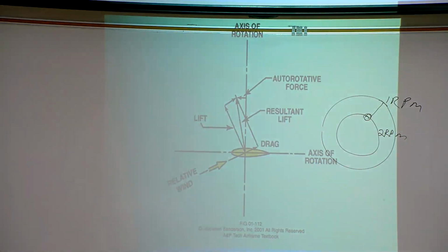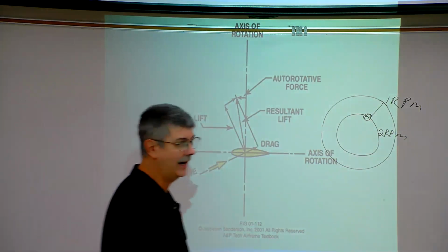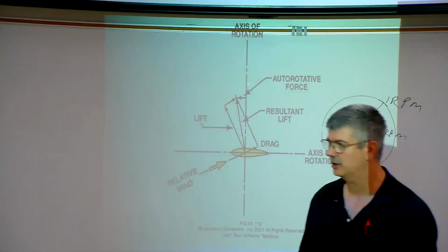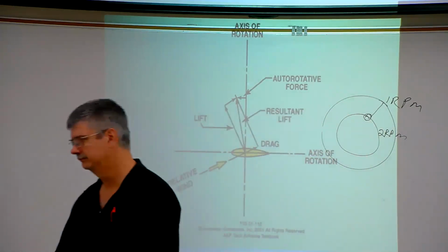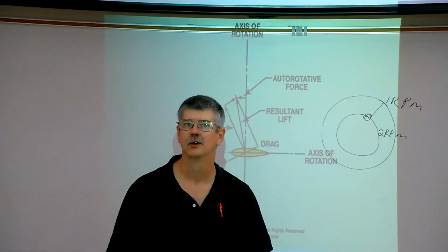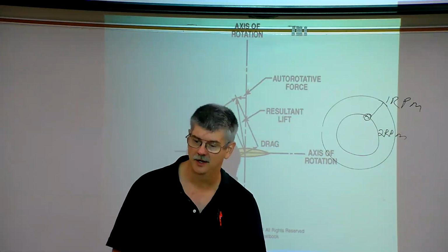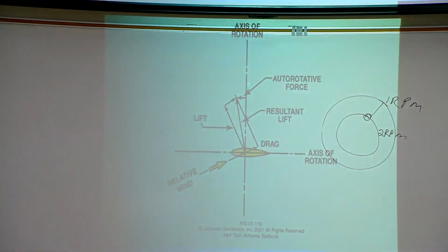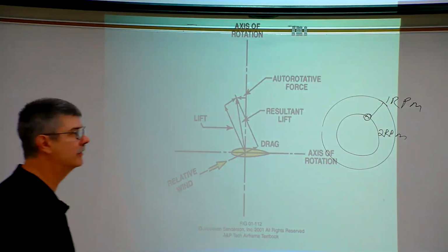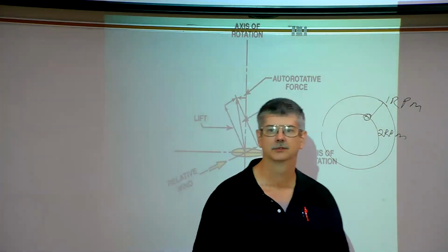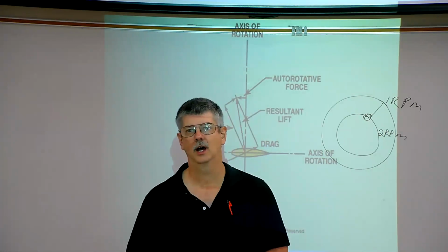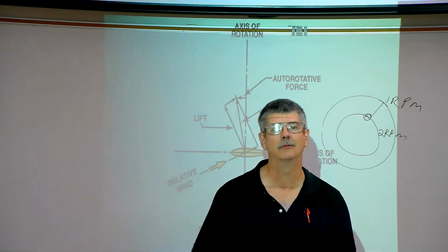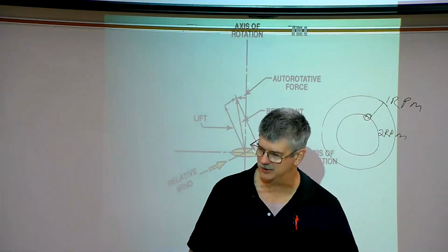The problem is, over time, the rotor blades got larger, they spun with more rigidity in space. And because of that, trying to move it got pretty much impossible for the pilot, and thus, the advent of the pitchable and what we refer to as a swash plate.